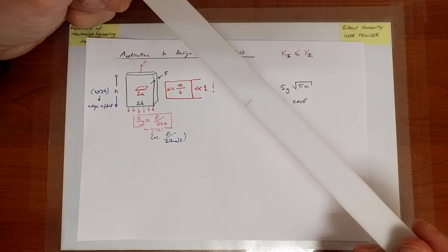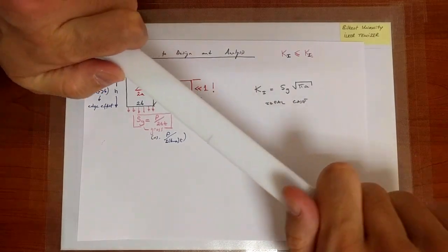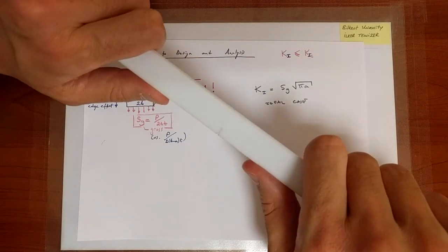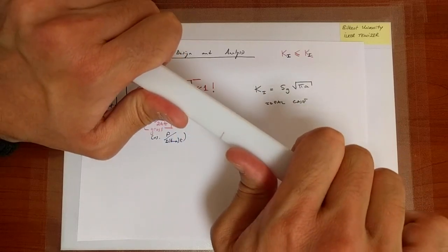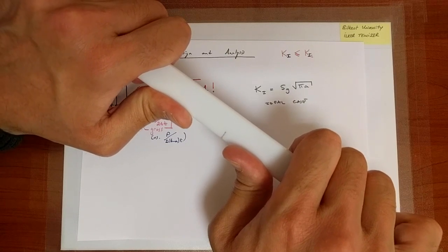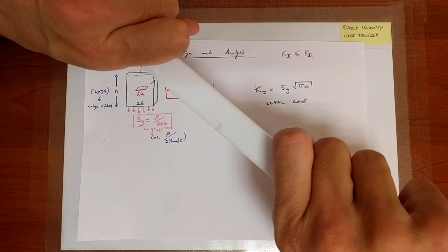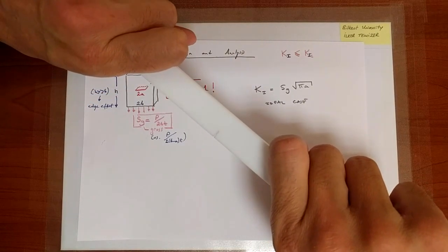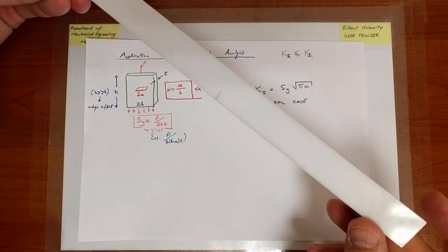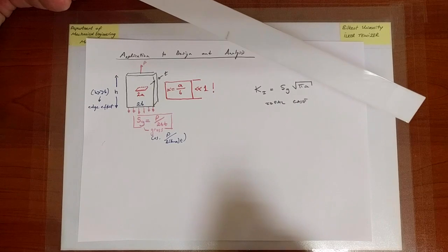Now, third, I don't need to only pull on this plate. I can also try to bend it, and that's exactly how I broke it, right? And notice when I'm bending it, I'm not going to try to close the crack, because in that case, there will be no stress concentration, there's no tension, so there is nothing to consider with respect to fracture. I need to bend it in such a way that I try to open the crack surfaces, move them apart from each other. So when I bend it, it's not tension, so it also doesn't fit that scenario. So even with a simple geometry like this of a plate, I can easily deviate away from this ideal case.